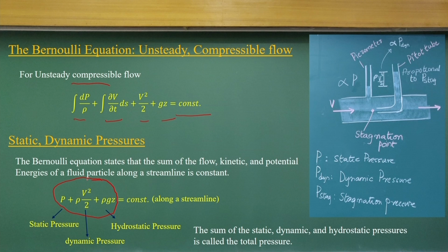As I discussed earlier, it is the summation of three energies. Flow energy is because of the pressure at that location, how much work is done by that pressure. You have a velocity field, which has kinetic energy, and the fluid particles, or virtual fluid balls, staying at a particular height from a datum, which gives potential energy.